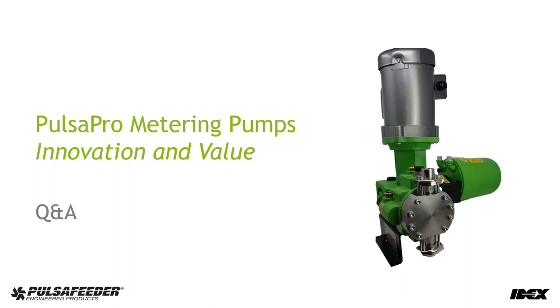And in that case, under normal operation, you want to see oil pulsating inside that window. So hydraulic bypass, you don't want to see anything, and if you do, you got a problem. In the push to purge and its diagnostic window, you want to see it, and you want to see nice, clear, honey-colored oil in there without any air in it.